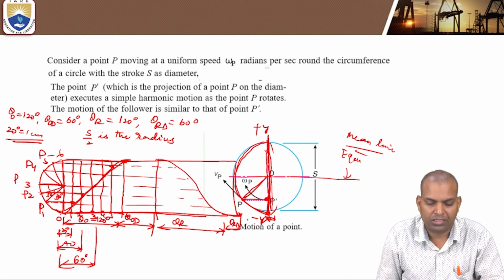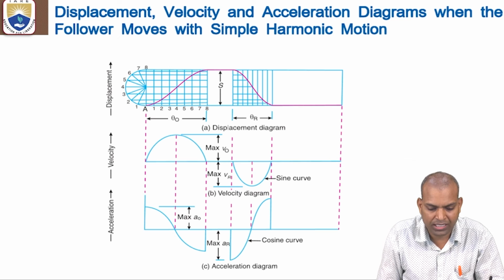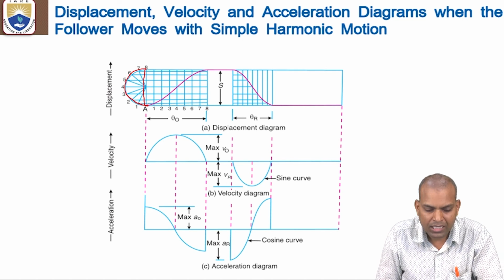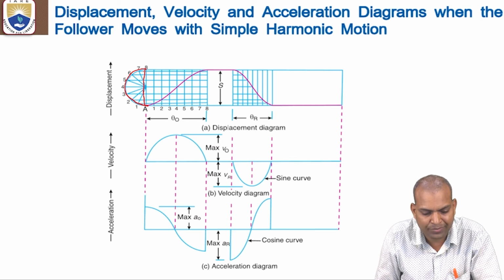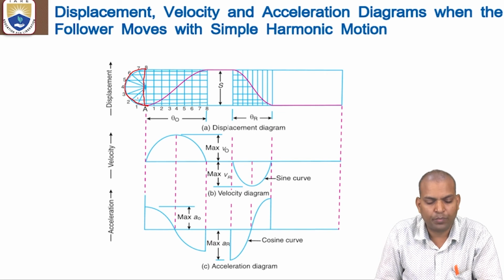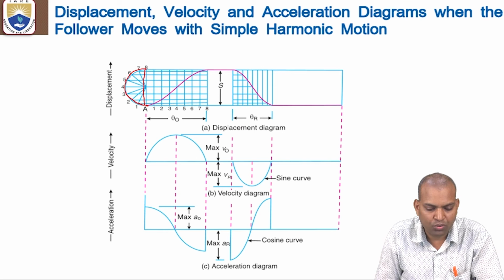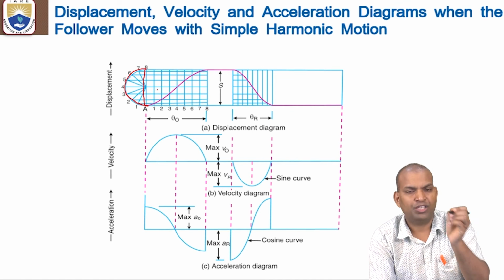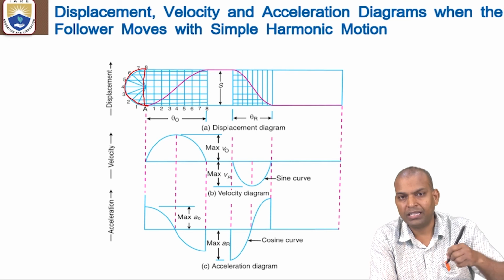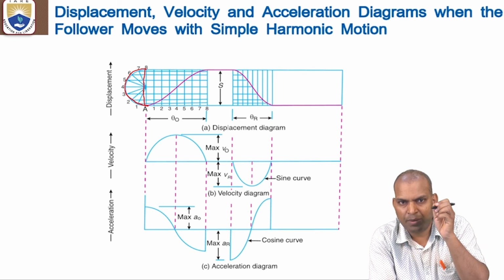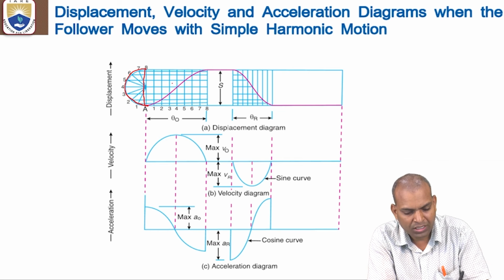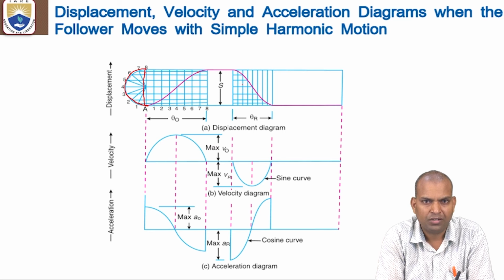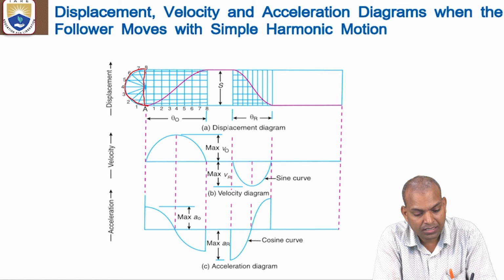Why do we have to draw a semicircle while drawing the projection lines? Here you can see why we have drawn a semicircle. During one semicircle, the projection of the point P moves from down to up. Rising takes place during the outstroke. The same circle, it moves on the same path, but then it becomes what? Return stroke. The same path is taken by the same points, no? That's why the same projection of the points here will project onto the return stroke. But generally, it should be a complete circle.